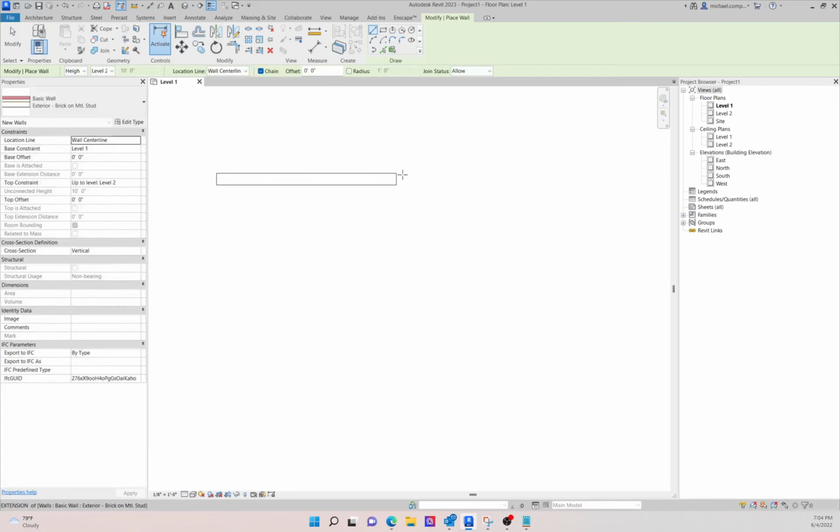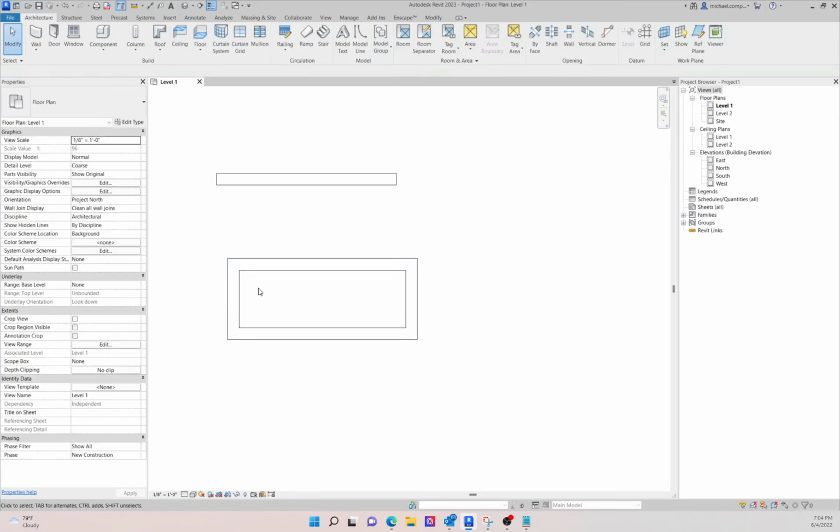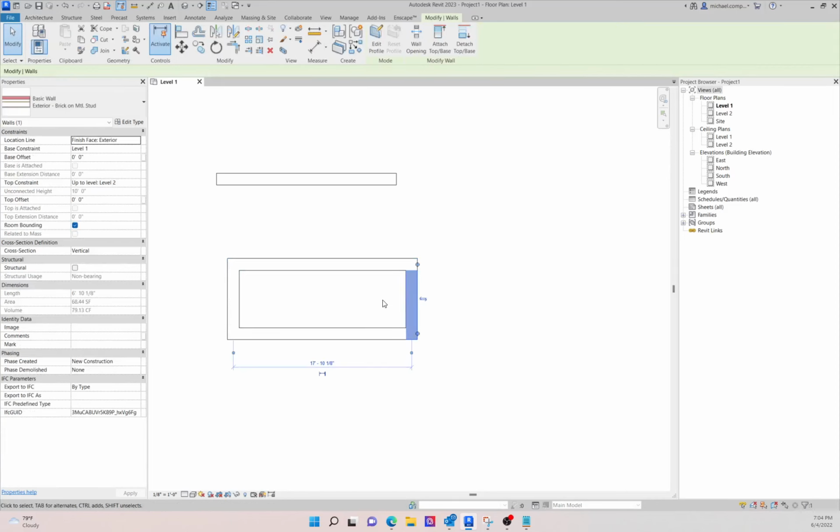If I really wanted that to be exterior, so I know the dimensions of the thing I want to be, I'm going to choose the exterior, so that when I turn 90 degrees, I'm not having to do math in my head. I know what the overall dimensions of this thing are going to be, and then I know it's accurate to that dimension, right? This is the other way you can do this, is just draw it and edit those dimensions later by clicking these toggles and put in the number that you want it to be.